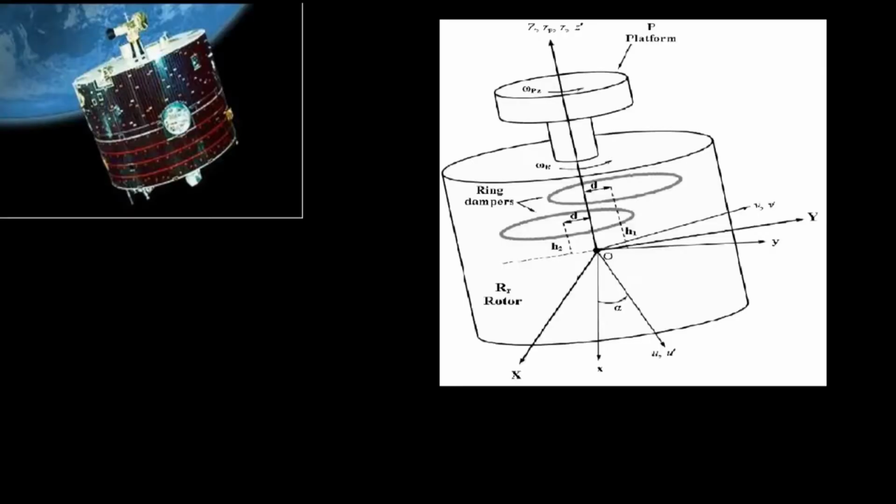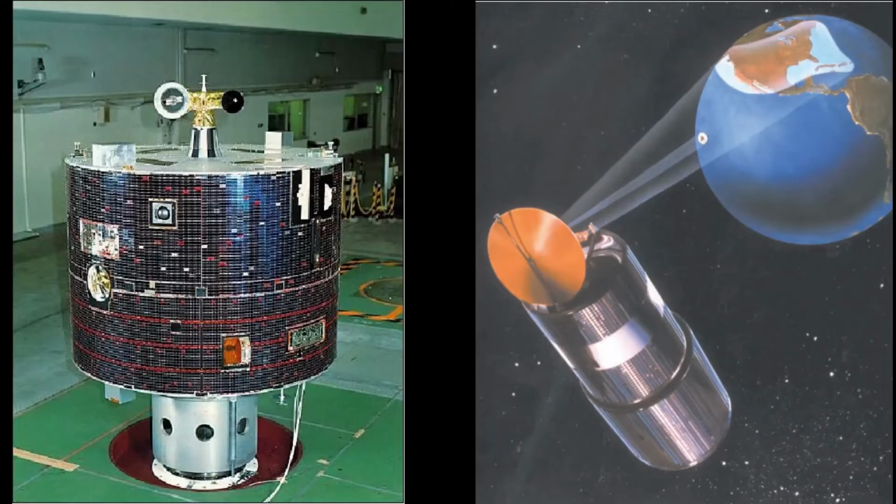These systems consist of two cylinders, one inner cylinder surrounded by an outer cylinder that is spinning at a high rate. This cylinder provides overall stability, and the inner cylinder rotates at a much slower rate. For example, if a spacecraft is in geostationary orbit, the inner cylinder will rotate at orbit rate once every 24 hours, keeping the sensors and antennas focused on Earth.